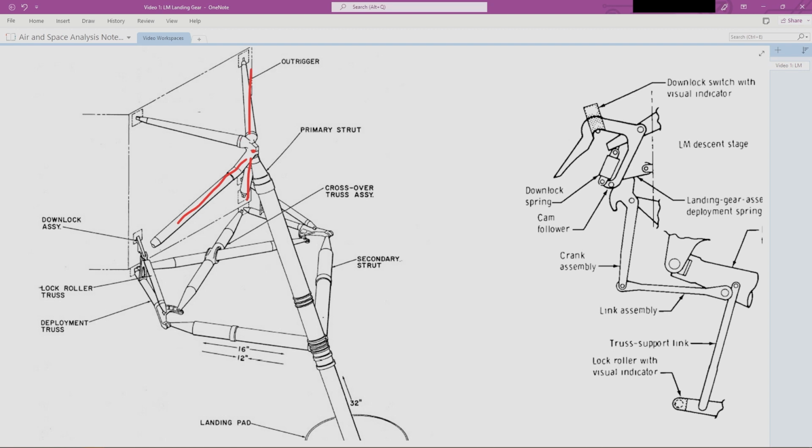Like if you're setting up a camera tripod, your tripod only has 3 legs, because you can have a stable 3-leg structure like this, and as long as you do your joints right at the confluence point, then essentially you'll have a fully defined structure that's fixed in space. And strut tripods are fairly common from what I've seen in spacecraft. So why did they add a 4th strut?